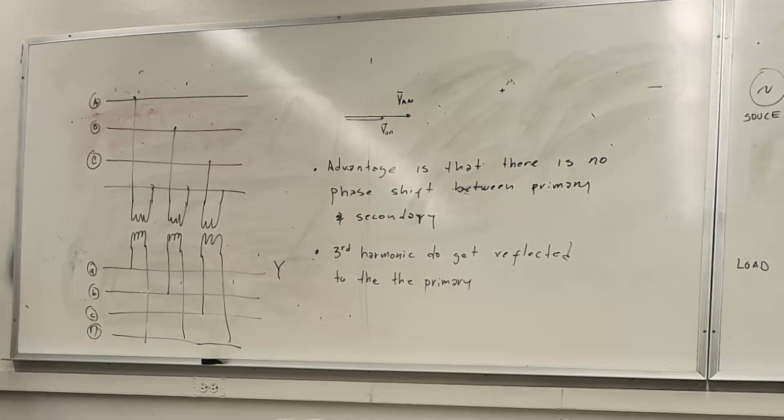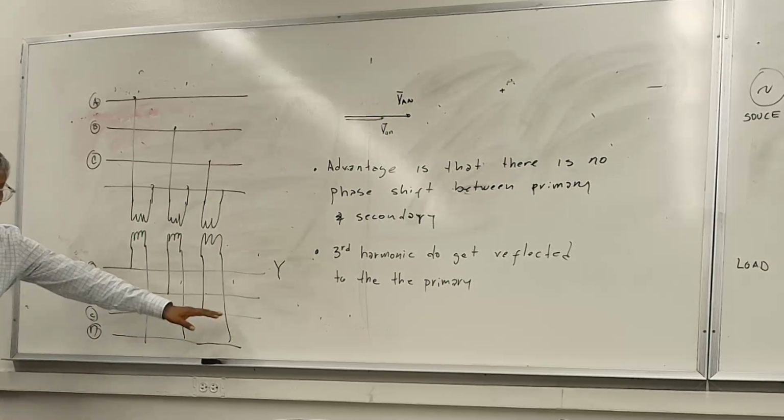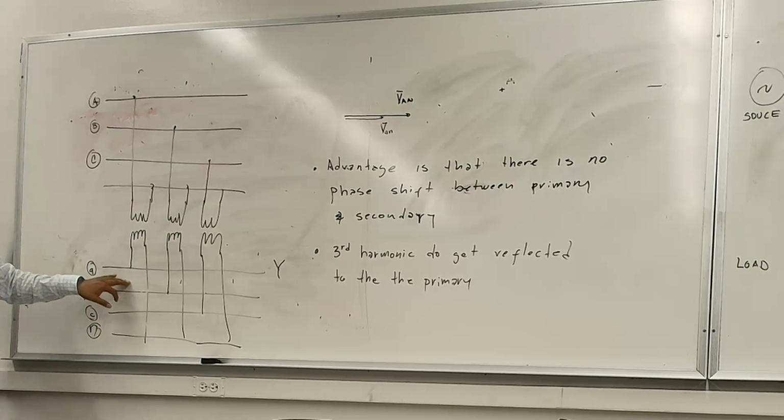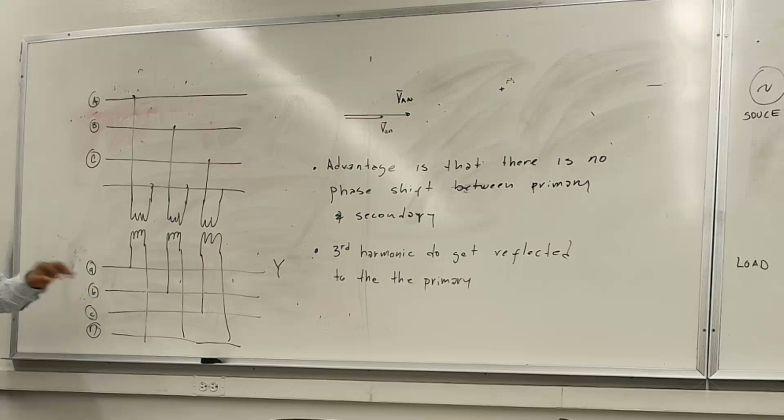The other thing is all of the rules that we have in place, right? When we have nonlinear loads connected, maybe, I'm gonna think of, say, 10% of your loads on a distribution system are nonlinear, right? Well, that's not the case anymore because as you start adding battery chargers, solar PV, electric vehicle chargers, those third harmonics or even harmonics continue to increase.